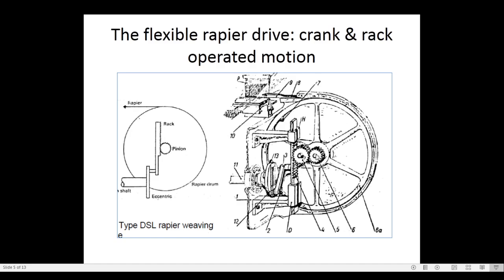When the flywheel moves clockwise, the rapier head, the rapier, goes in the housing. See, the housing is there. The rapier tape is flexible, and it goes inside when it moves clockwise. When this flywheel moves anti-clockwise, the flywheel gives drive to the tape. Here teeth are there on the big wheel, meshing with our tape. The tape goes as this moves anti-clockwise, inside the shed up to the center of the machine.